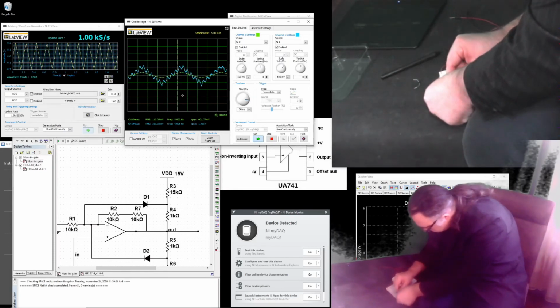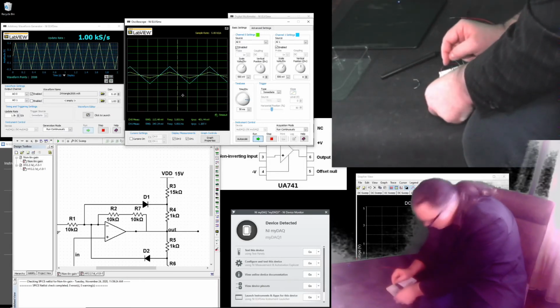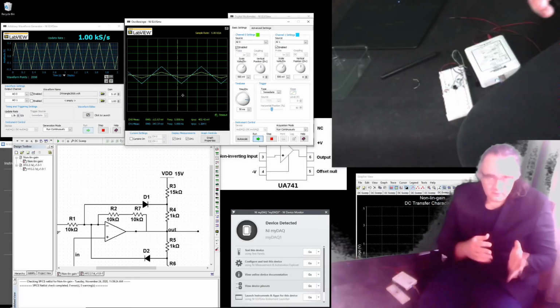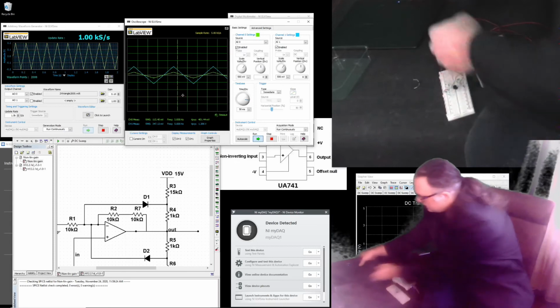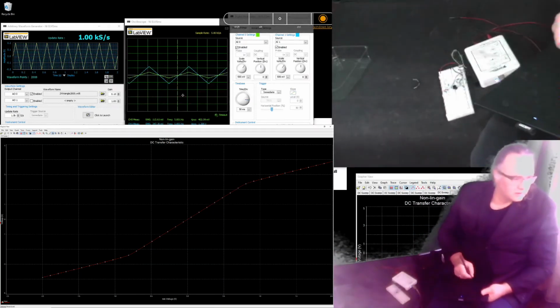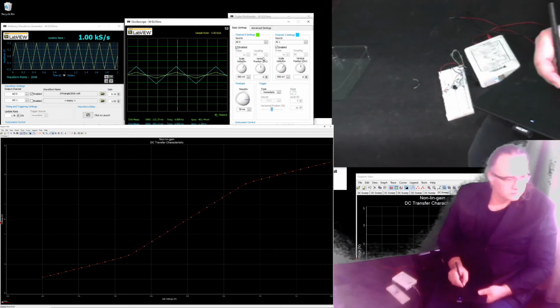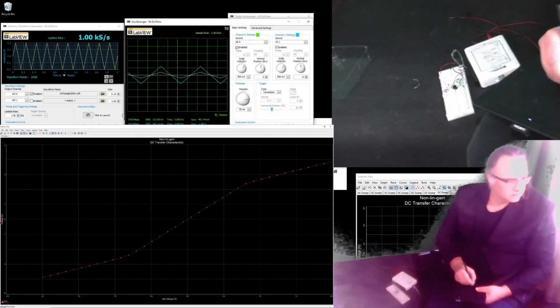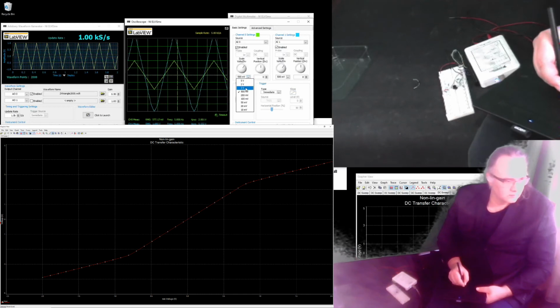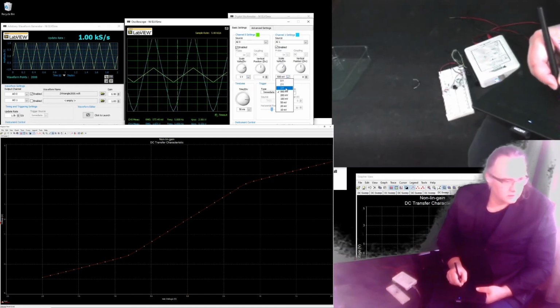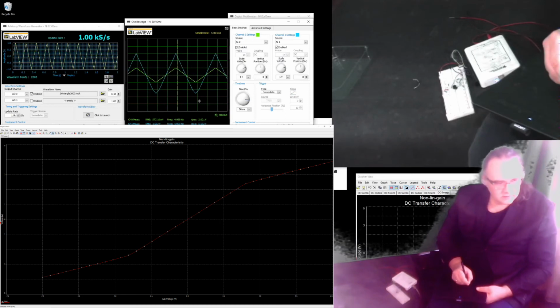So this is to clip the bottom part. So one diode now is connected. Nothing changes in the waveforms because the amplitude is small. But now if I increase the amplitude here through the gain, I'll reach a certain point for which the output signal is too high, and then the diode starts activating. You see that it works.